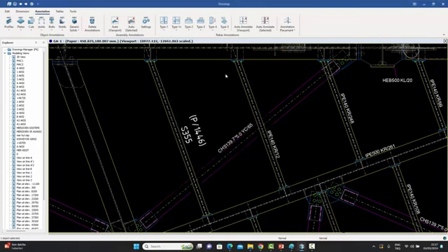So you can create as many custom annotations as you want. You just provide a category for them, whether they belong to profiles or plates or bolts or rebars, etc., or generic solids, etc. And once you're done, automatically the program will categorize them and they will appear under the proper headings.